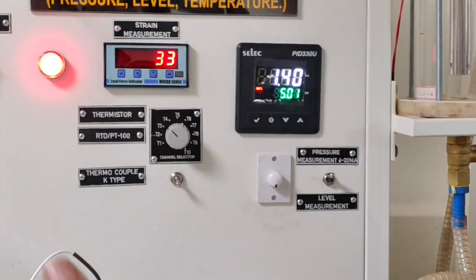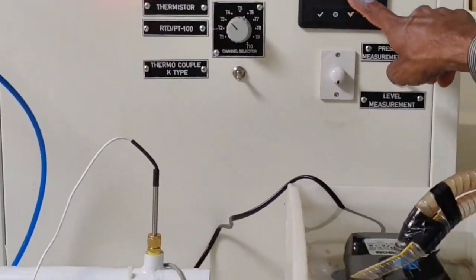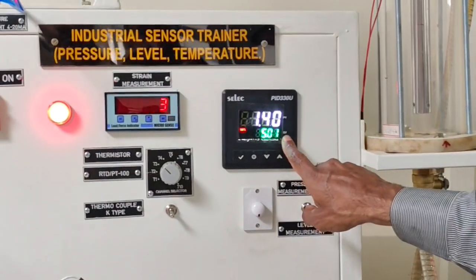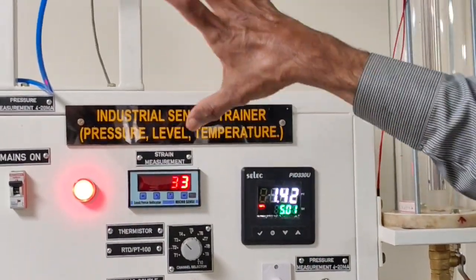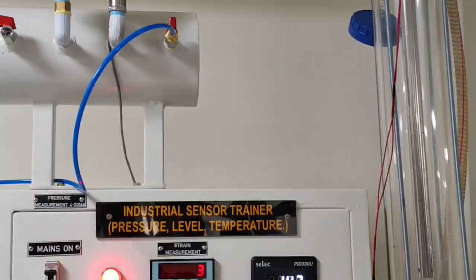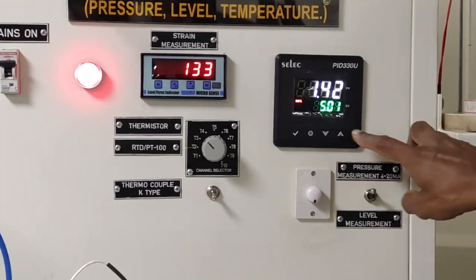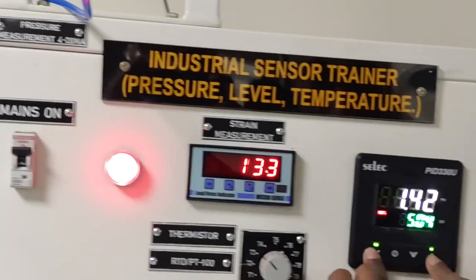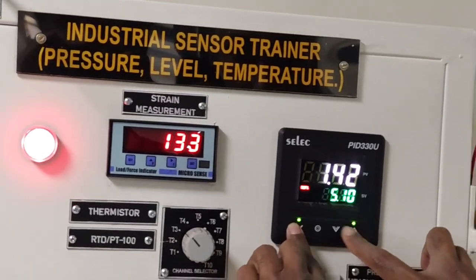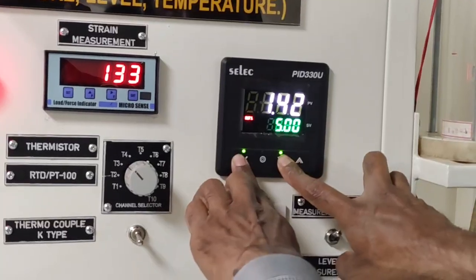Anything you want to make it, you can connect to the compressor. This has 2 parameters, set value and process value. The process value will always indicate the present pressure. For the set value, if you need to cut off at 2 bar only and not raise further, you have to set it for 2 bar, and hold it. You can reduce or increase whatever setting value you want. I will show you in the level also.